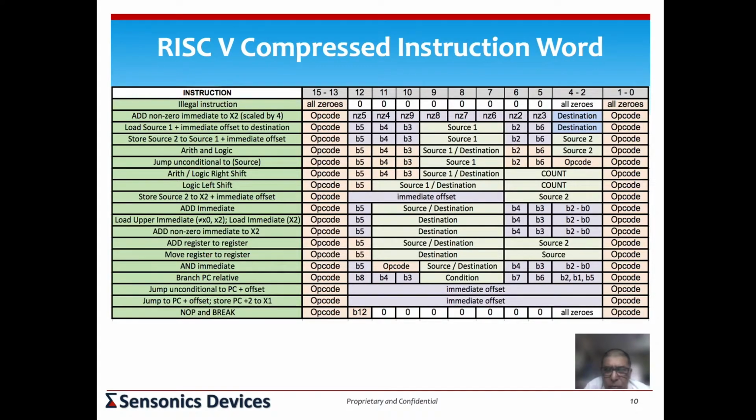And when there are two options provided, when they are 0, 1, 1, 1, then that will be a 48-bit instruction. So excluding those codes for those 5 bits, the rest are available for 32-bit instructions. So you can keep expanding on the instruction word simply by looking at the LSBs, and you can decode what they are from the LSBs, and the decode depth is only a 5-bit or a 7-bit single gate. This is how the thing has been set up.